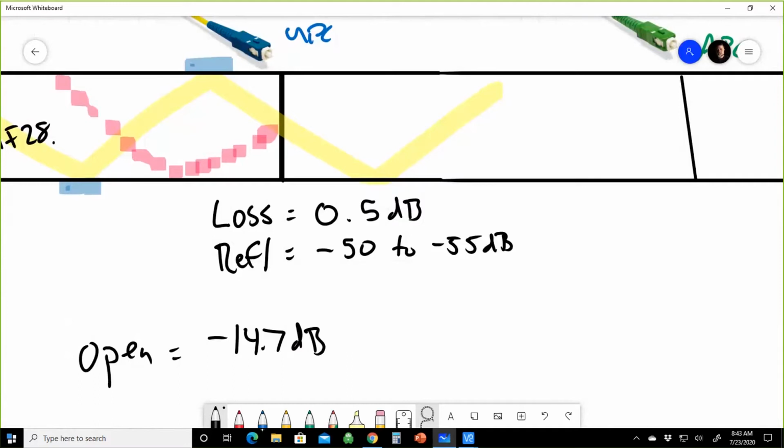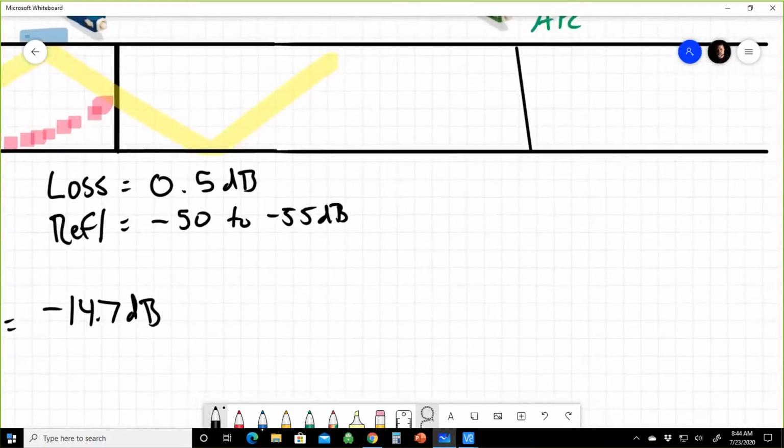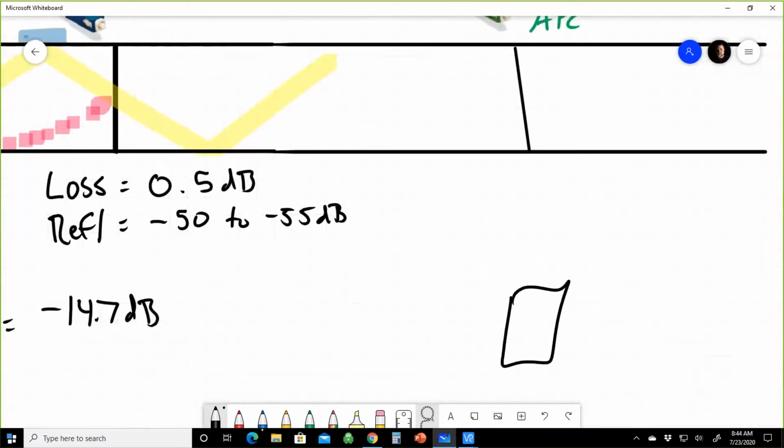So typically when we go to a site that's taking errors, you'll get a call from the test center or the NOC saying, hey, you're taking dribbling errors at this particular remote amp site. You drive out there. The first thing you do is you get out your power meter. You unplug the fiber from the receive card and you plug it into the power meter, and then you read light levels. And your light levels will say, hey, I'm getting -15 dBm. And for most systems, -15 dBm is pretty decent light, right? Depending on the receiver sensitivity. So what do you do? You clean the fiber and you plug it back in.